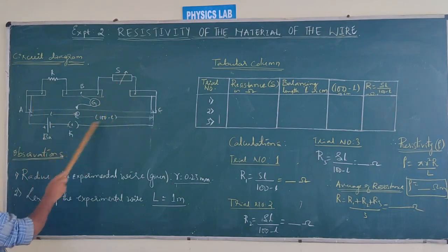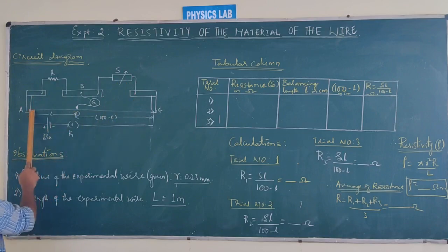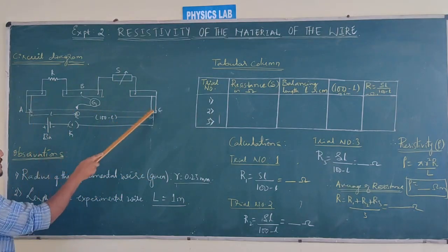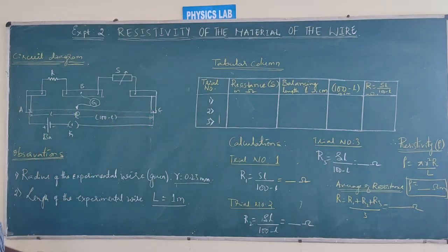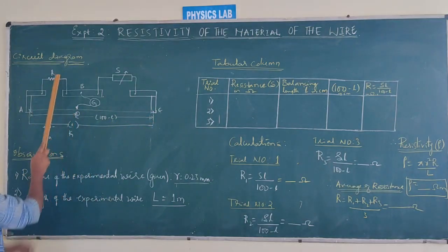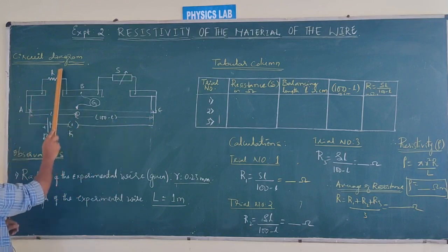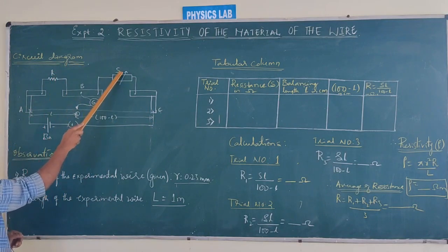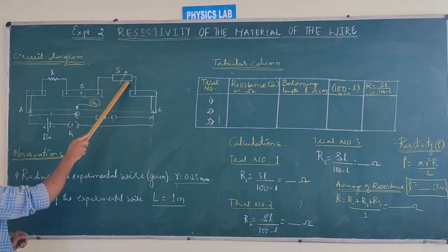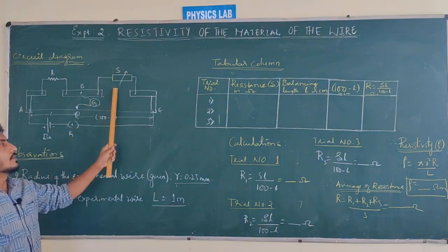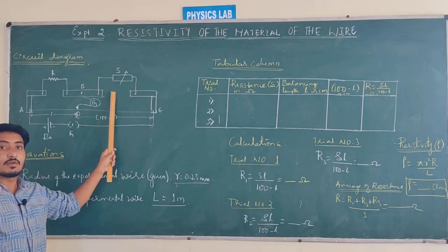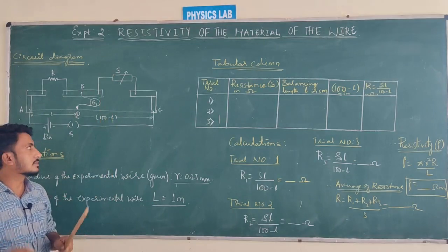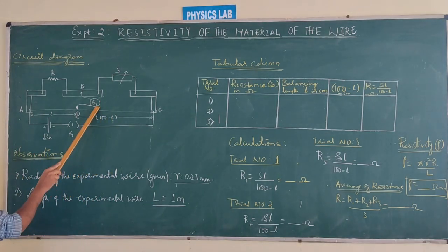See, this setup is called what? This you can see. This is actually a wire on the wooden stick. This setup we are calling it as what? Meter bridge setup. Here we have a resistance of a wire whose resistance is unknown, that we are pointing to as R. Then S is what? A variable resistance box indication. The arrow indicates what? It is an example of variable resistance. Okay. S is the resistance which you are removing from the resistance box. Okay, and G indicates galvanometer.